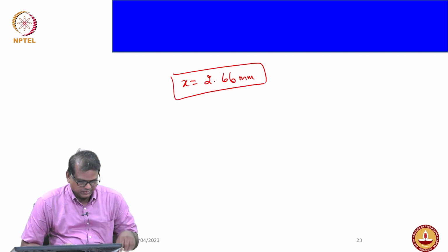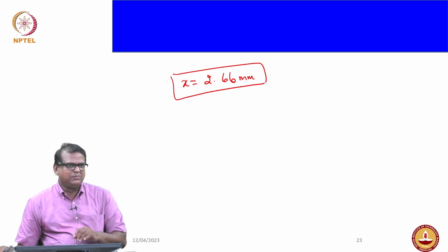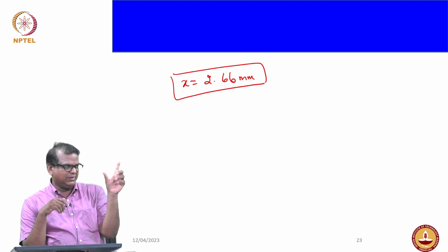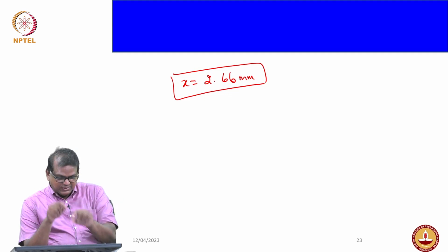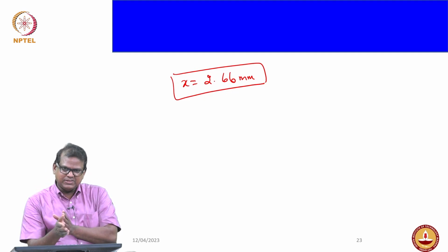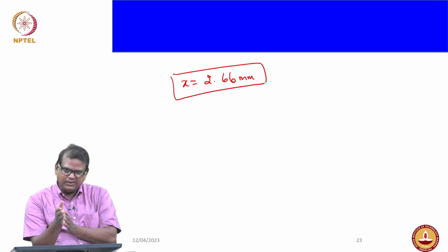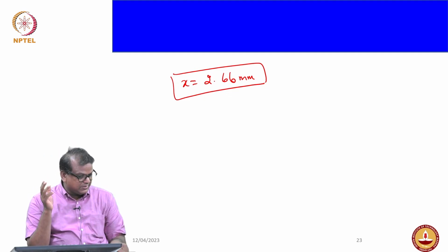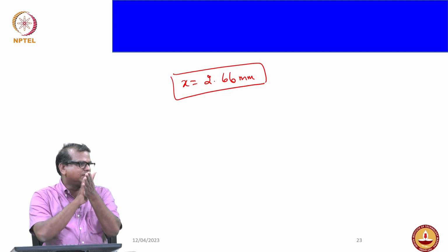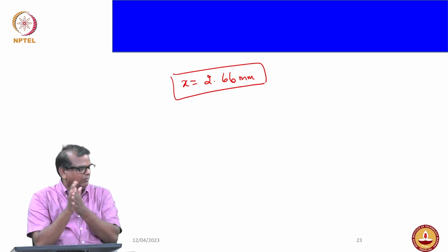So what do you understand now? We do not know the thickness of the friction lining, but this much thickness needs to be worn out. When this much thickness is worn out, due to the drop in pressure to 374 Newton, that is the place where the clutch cannot perform anymore. Until then it will perform.